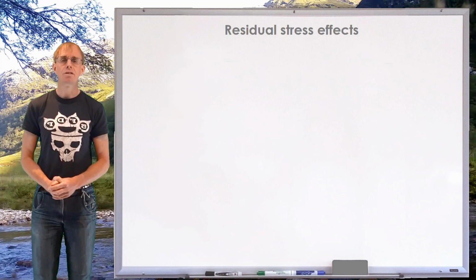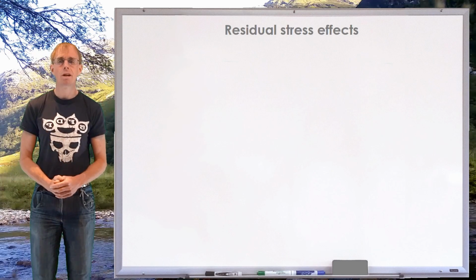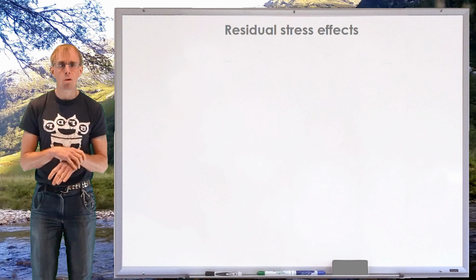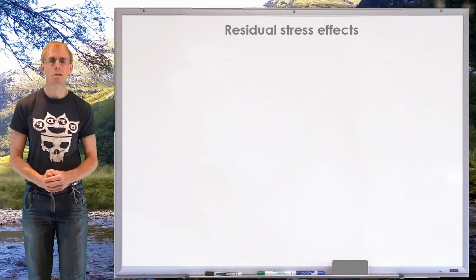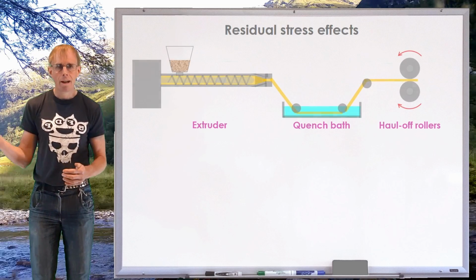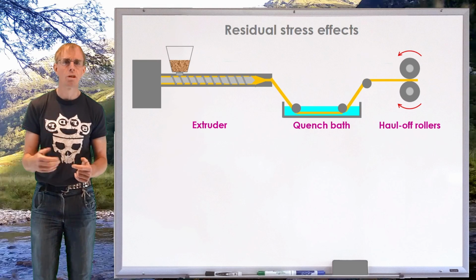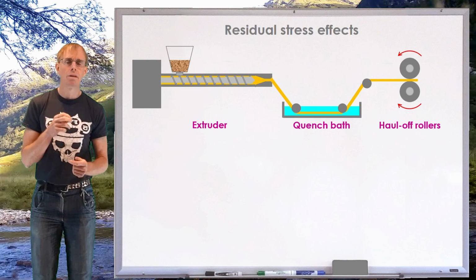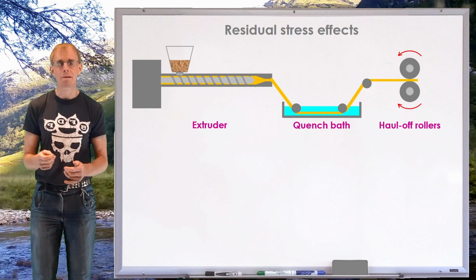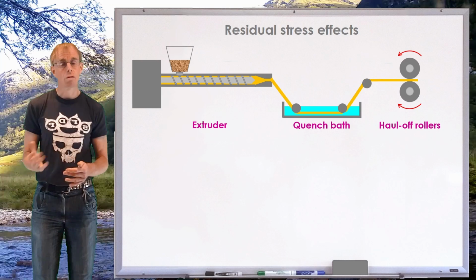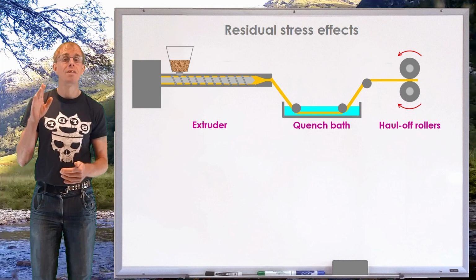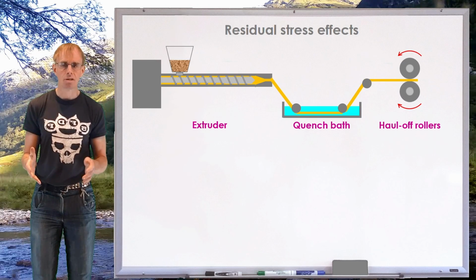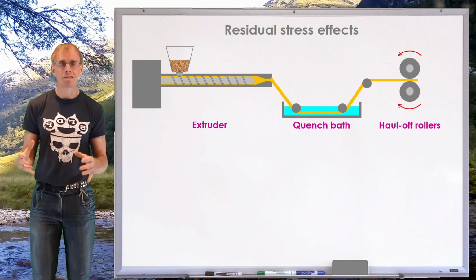The final thing I'd like to bring into your consciousness at this point is the problem of residual stress. Up until this point, we've talked a lot about the flow of the liquid phase, when the polymer is in the melt state, and how it's flowing through the die and how it might be subject to vortex formation or extrudate swell. But we need to think as well that viscoelastic liquids have time memory, and so they remember stress. Stress takes time to build up. Stress also takes time to decay once the factors that cause the stress, a shear rate field, have been released. So this really concerns the polymer as it exits the die.